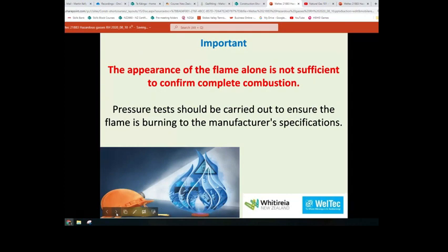Just looking at the flame, if you're doing commissioning, which you're probably not at this stage, just looking at it visually is only one indication. That won't necessarily tell you how the appliance is performing. So carbon monoxide detectors and testing the flue system's operation are other critical checks that must be done as well.